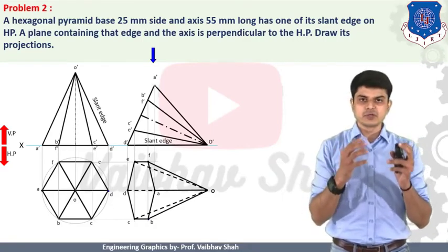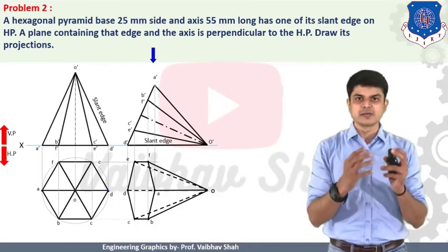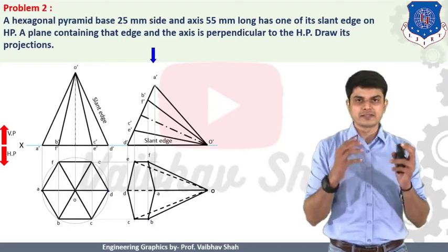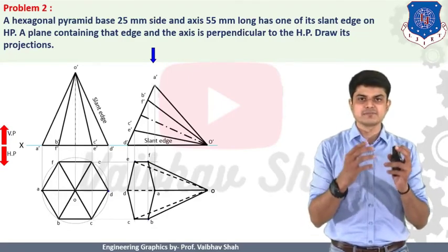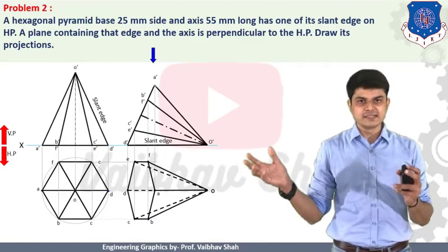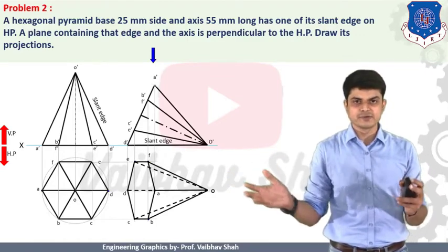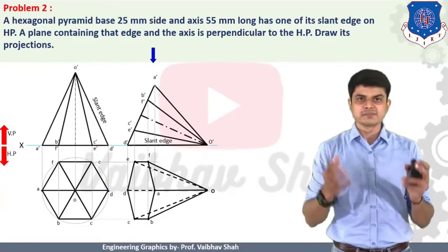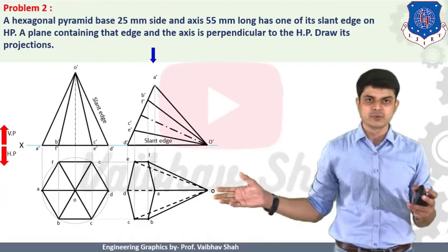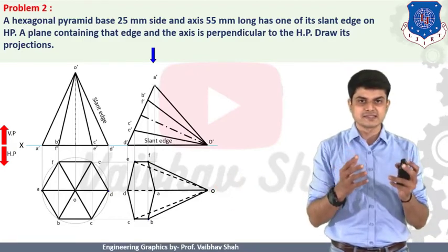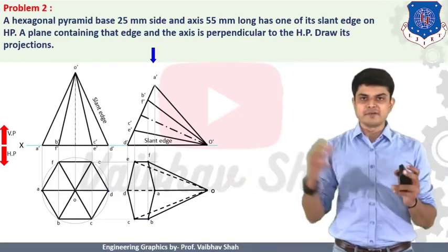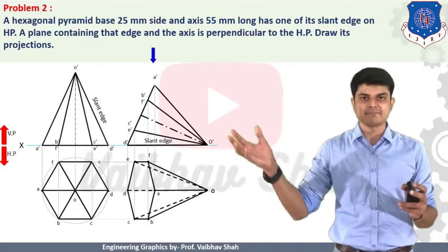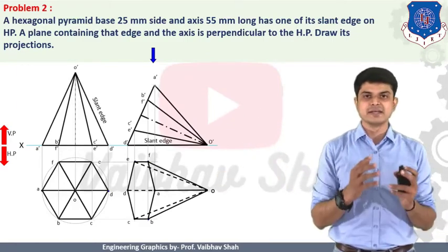And if we don't know how to draw the hidden lines, we certainly know that of two intersecting lines, both can't be full lines. For that, one line must be a hidden, dotted line. We know that the base is completely seen, so it is solid. So it is obvious that the line intersecting this base, that means this line OE, must be your dotted line. In this case also, since the base is solid, the line connecting point O with point C must be your hidden line, because we know that the base is completely seen in this diagram.